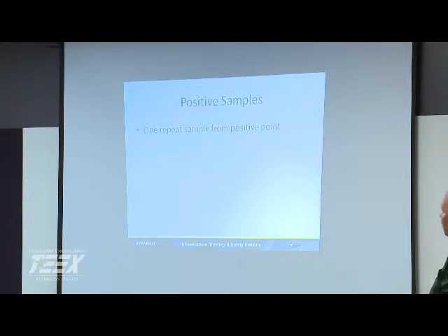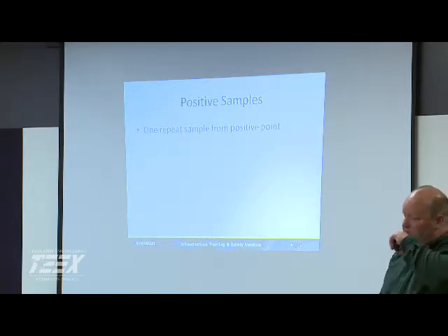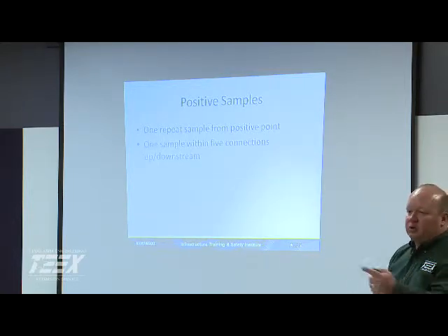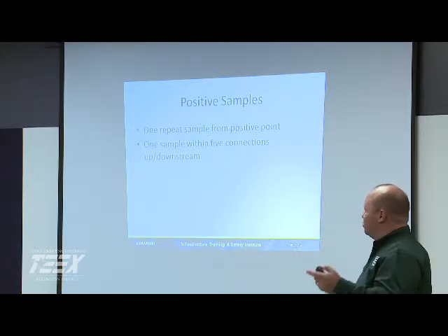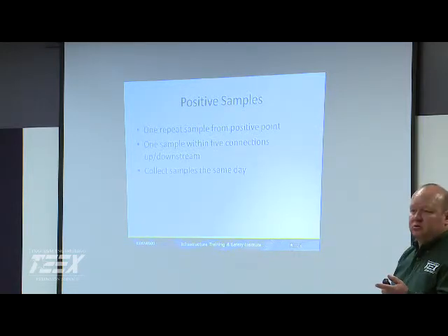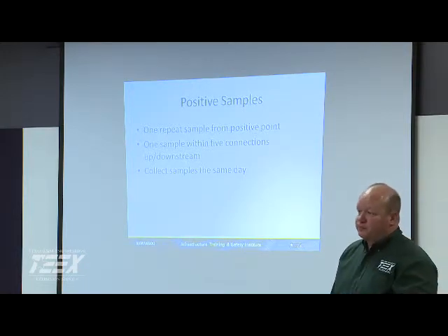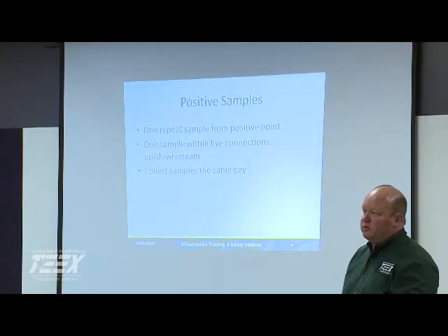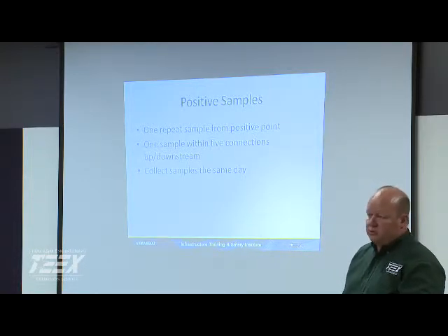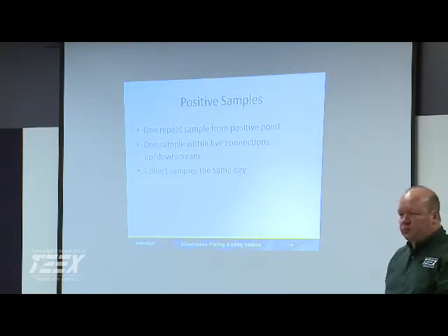So what are we doing for positives? You've got to repeat from the sample. You're going to do one up, one down. Y'all doing source water? Y'all having to do anything at your point of entry? True groundwater systems that opt not to do the log removal, then they've got to do a source water sample. On surface water, there's no source water sample requirement. Okay.